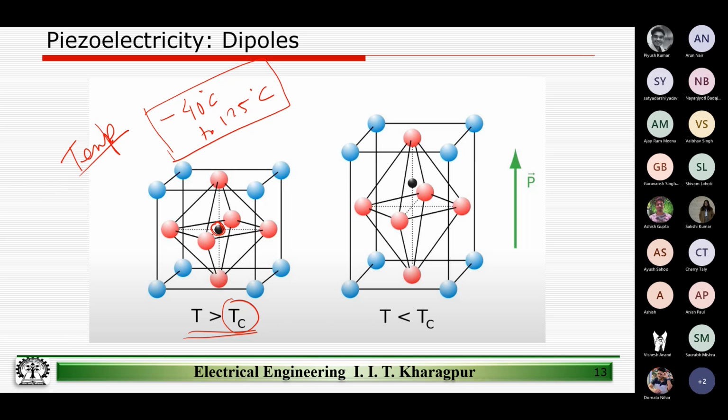degrees C. And if we have the Curie temperature somewhere in between this range, that's not a good thing to be, right? Because then the property of the transducer becomes some function of the temperature, which is not desirable at all, right? If we are designing a transducer to measure force, we want it to be dependent on only force and nothing else, right? We want it to be independent of temperature. So the goal is to realize material with higher and higher Curie temperature.